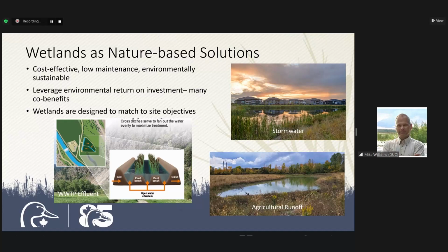There are many different kinds of treatment wetland systems. Some are designed for treating stormwater, some to treat agricultural runoff, and some to treat wastewater. And when you get into wetlands that are specifically designed to improve water quality, they aren't necessarily that attractive to wildlife, as they don't provide a rich, interspersed aquatic plant community that provides cover and food. At the NSDF site, the CNL team was interested in nature-based solutions to improve water quality and lower future maintenance requirements, rather than to attract wildlife.